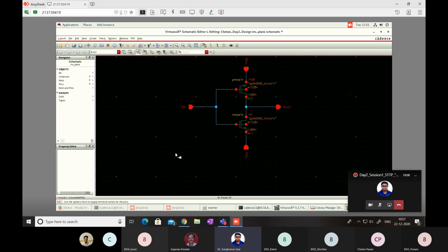Okay, fine. Now you can see your circuit is complete. Now I go for check and save. See, no pop-up window is open, so it means check and save is complete with no error. You can see here the log file, right? Always see the log file. Whenever some error occurs, check your log file. There it will show the error. Now you can see in your log file there is no error. Yes, Chandrakanta sir, I will come to you within 5 minutes.